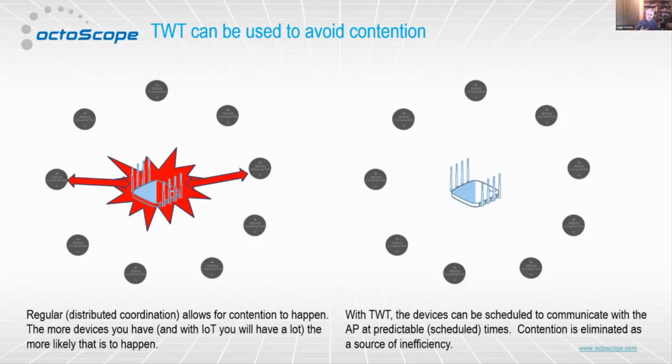So essentially, the AP and the station negotiate some stuff, and they're like, okay, now we're going to have this sleep-awake period, and that starts at this point. And the point at which that starts is based on a timestamp that is sent by the beacon. So essentially, the station is getting the TWT timing from the infrastructure, from the AP. So they kind of synchronize each other. Again, I'll let Jim jump in on that when he does the demo, but I think that is a reasonably accurate answer to that question.